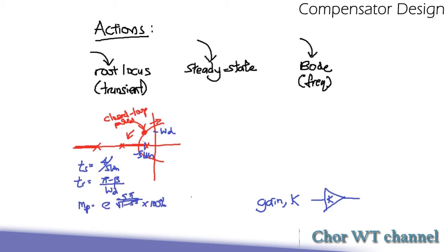You will see that the closed loop poles here have a tremendous effect on the transient performance measures that we normally use, which are the settling time, rise time, and maximum overshoot. We then link the steady state error. Say here, we'll be using the steady state error for unit step response, which is A over 1 plus Kp, and our Kp is the limit as s goes to 0 of C(s)G(s), where C will be replaced by a gain K. You can obviously see from here that by adjusting the value of the gain K, you are actually adjusting the value of Kp, and hence it will affect the steady state error. In general, the higher the value of the gain K, the smaller the steady state error will be. But usually, increasing the value of the gain K will cause the system to be more unstable.